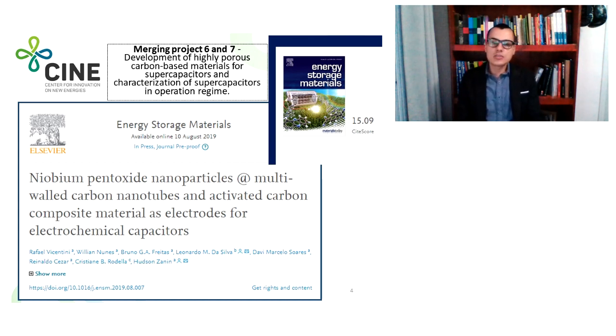So, during controlled experiments, we investigated the influence of different working potentials on the supercapacitor. The electrochemical performance of these carbon-based materials decorated with niobium was evaluated at 1 volt and 1.8 volts in a symmetrical two-electrode cell at room temperature.